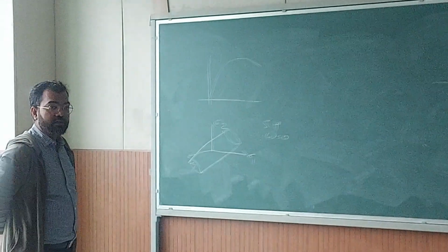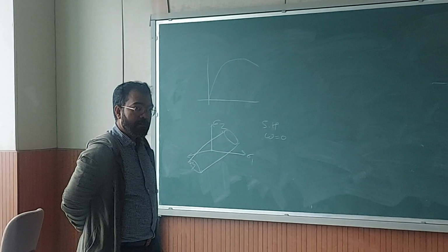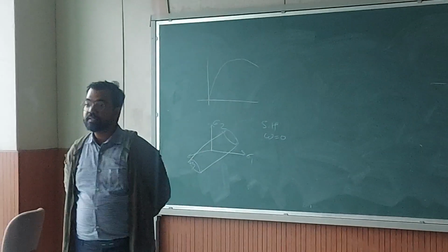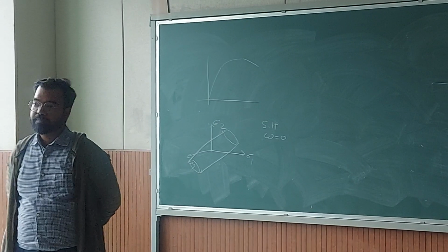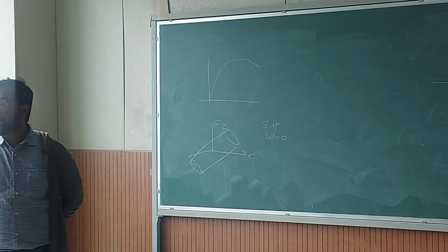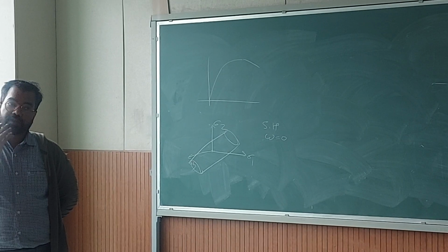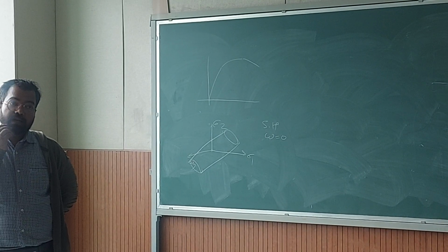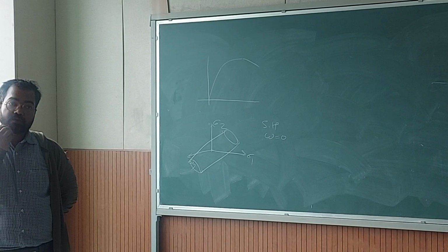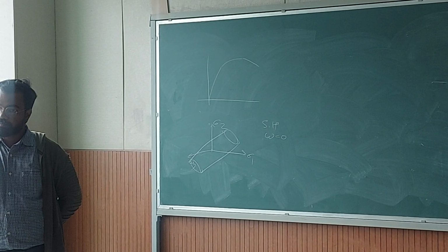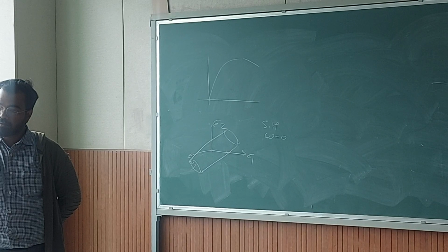So the same concept goes and resistivity will change, right? Because the resistivity will change, you can measure the voltage drop, and by the voltage drop you can measure the resistance change, the resistivity change, and resistivity will directly give you a measurement of the damage which is happening, right?